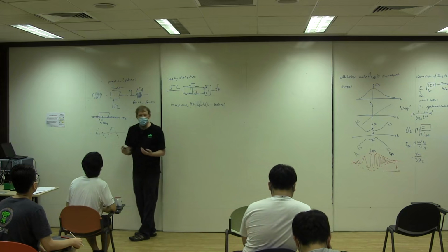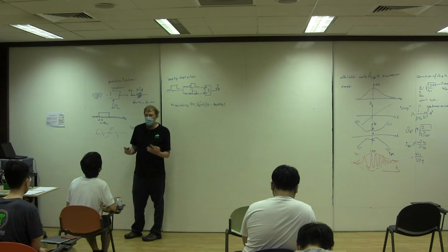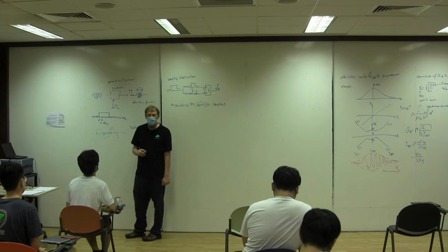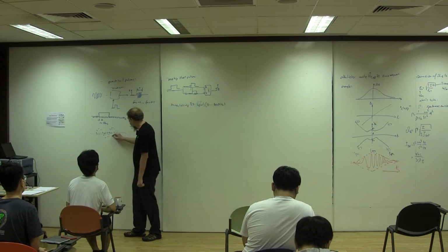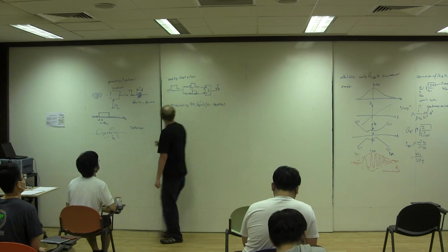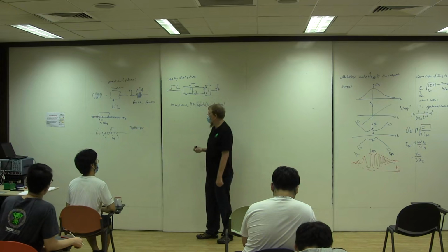Or a direct synthesizer. And you can make sine waves and start and stop those sine waves as you wish, with the resolution of your synthesizer. That's typically on the order of 1 nanosecond time resolution. So you would find it a bit difficult to get to higher frequencies.